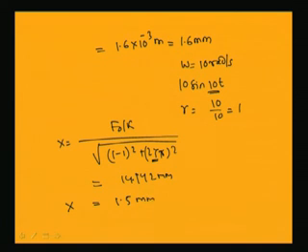So, you can see that at resonance condition the response is coming to be 14 point something, very high in comparison to the response when it is away from omega equal to omega n. In the third case your r equal to 5 by 10, this is equal to 0.5.